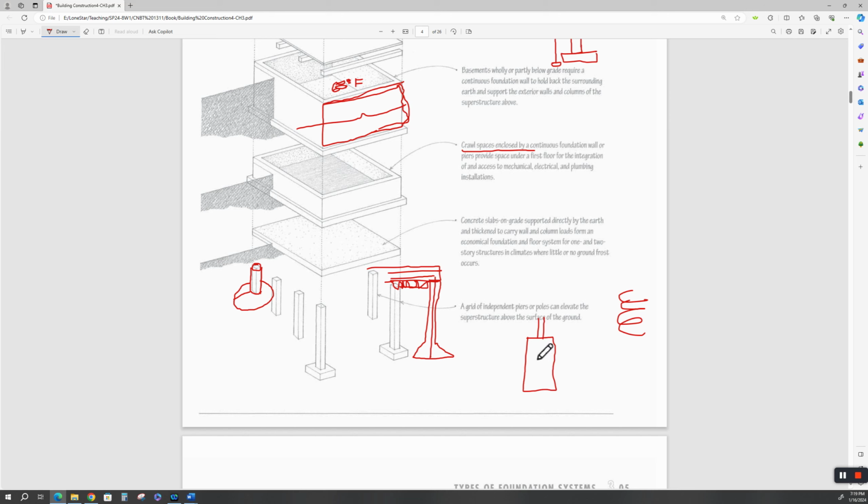And inside here is a centrifugal set of blades, two of them. When they spin it, these blades sling out due to the centrifugal force, and they cut the bell at the bottom. They stop spinning it, the blades come in, they pull it out, then they drop rebar in there and fill it with concrete.